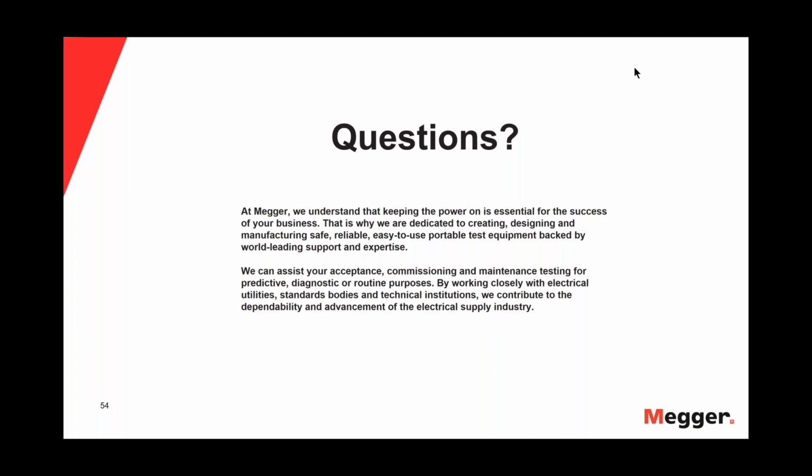Robert, Marshall has used the term radar a number of times. What frequency does the TDR use for its pulse? Okay, here the term radar is an analogy. It uses the same principle, but the propagation happens on the cable, not through air, like an airport radar for the airplanes. So in terms of frequency, the pulse itself has a few parameters.